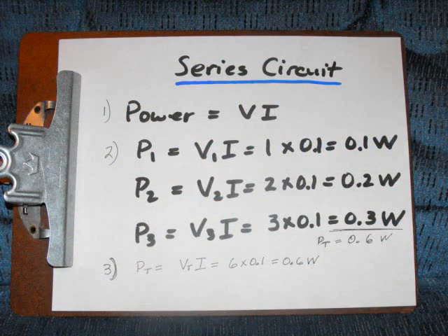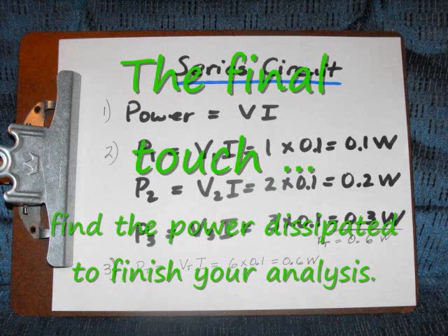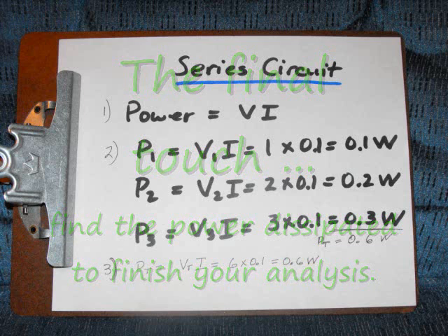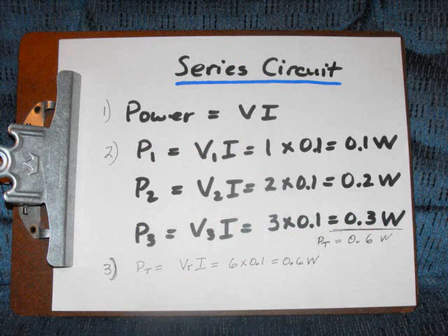Okay, well, all the money is in this one now, so power is where it's happening. Remember, we worked out that we could figure out the power if we multiplied the voltage times the current. Notice that when we work out the power dissipated by resistor 1, then we use the voltage that is dropped across resistor 1. You can notice also that in these equations, there's only one current. So probably the biggest thing to remember then for a series circuit is the current stays the same throughout the whole circuit.